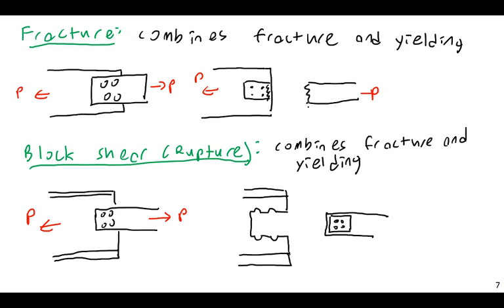The reason for this is to think of your failure planes. If this plate is going to tear clear across the cross section, the entire cross section here is going to fail in tension. Here, though, if I rip this piece out, along this surface it will be ripped out in tension, but along this surface and this surface, it will be a shear failure.